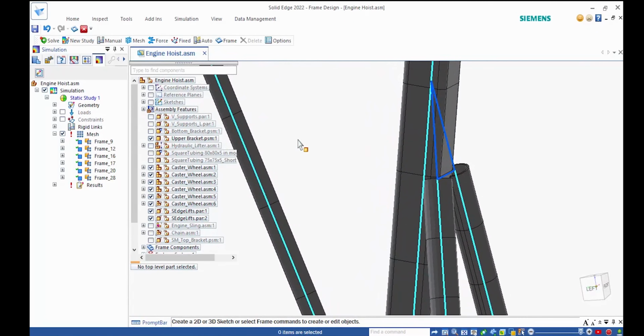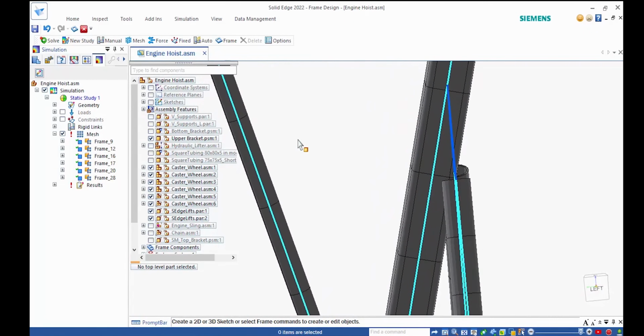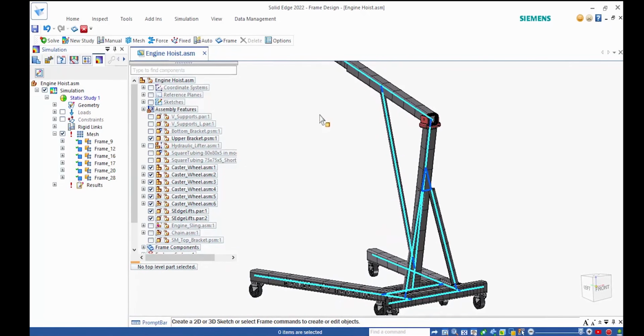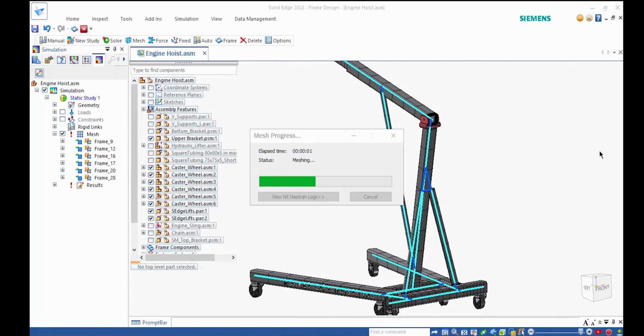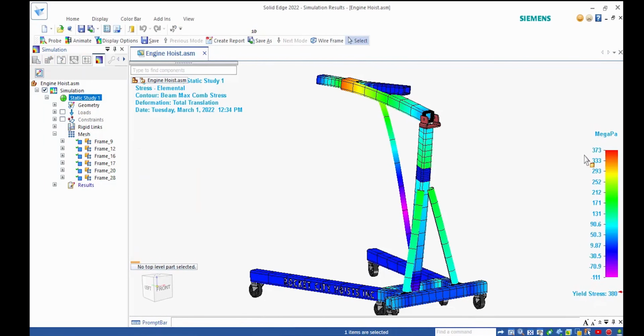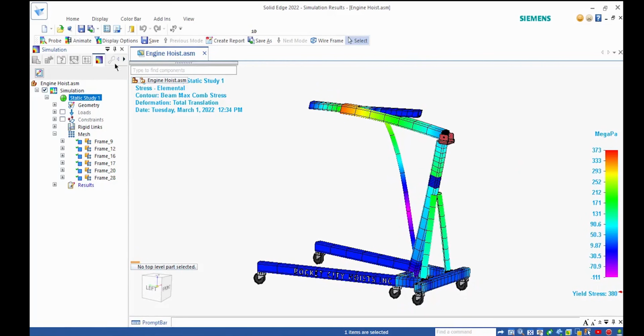It's not only created perfectly, but it also coincides with the plane if you create it through to the back supporting elements. Okay, now that we added that connector, we can solve it again. And as results pop into the post-processing window, we can see that we lowered stress significantly. Now we're very close. We're even lower than 380. We're at 373.